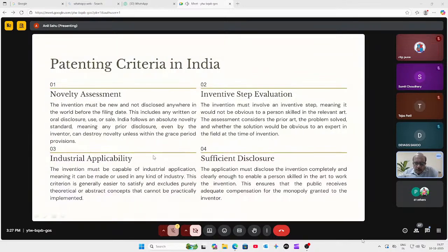Like in many areas, you find continuous failure of roads. After constructing the road, within one year or six months it fails or gets damaged, and you get potholes, because of the soil condition of that area, or because the site where you are constructing the road may not be good, or the capacity of the road concrete and stone was not properly selected. In areas near a river bed, you generally find the roads are not in good condition. Or where there is black soil, a road constructed on it gets damaged very quickly, you get potholes, and continuous maintenance is required.